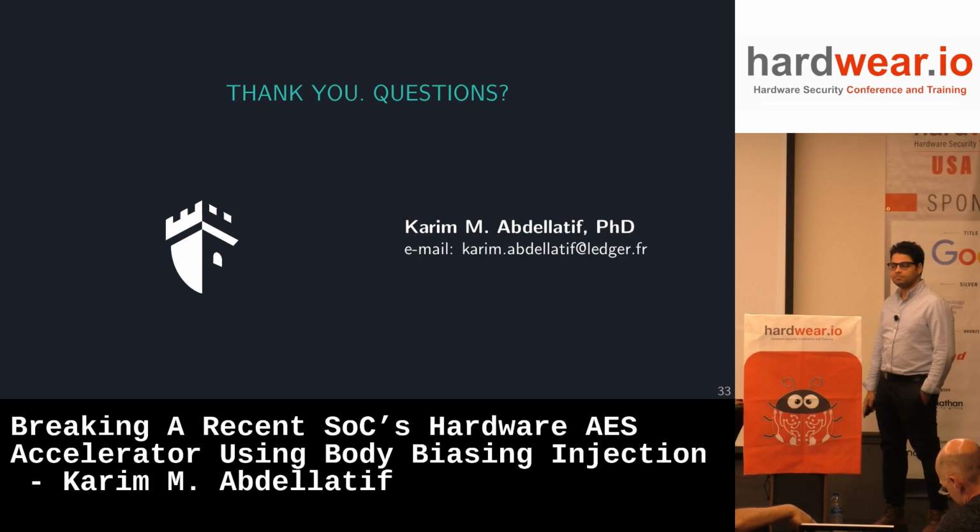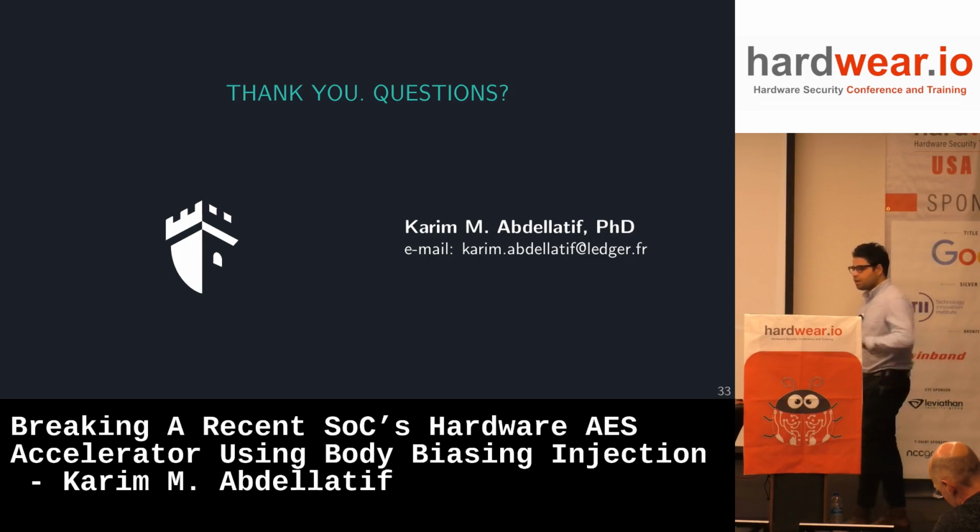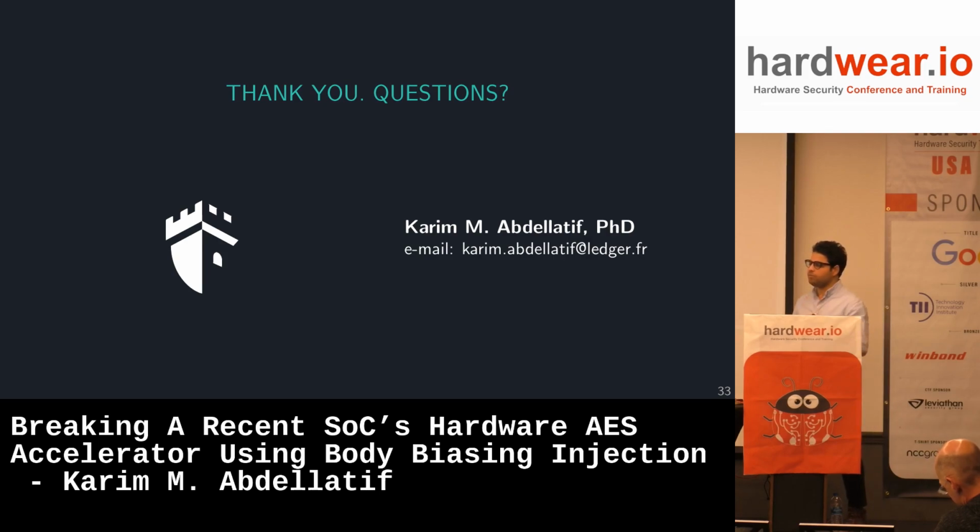What was your reference signal for your trigger? I can control firing at a specific time relative to something else. I can control the trigger from the firmware itself. So you've modified the firmware? Yes, custom firmware. The hardware accelerator, you can call it from the firmware, and after that you can easily add a trigger before and after the start of the AES.